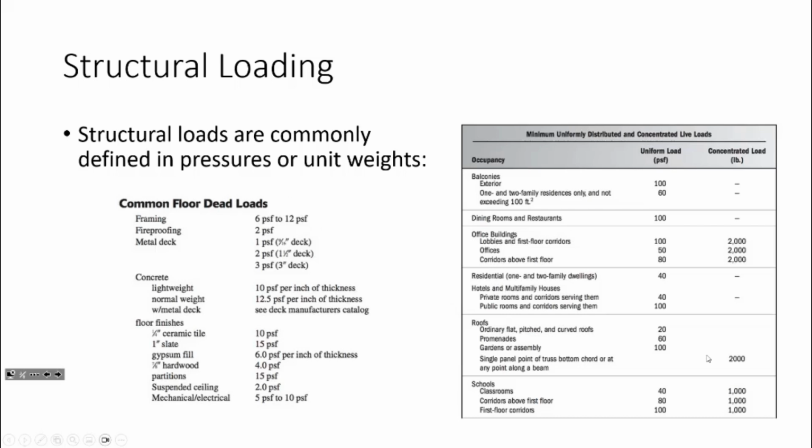So what it's being made of, what I mean by that is all structures need to be able to withstand their own self-weight, okay? As an example, if you have a building that's made out of steel, structural steel weighs 490 pounds per cubic foot. So we can take that 490 pounds per cubic foot and determine weights of the structure pretty easily as unit weights times volumes. Reinforced concrete weighs about 150 when you account for the rebar, and what have you.